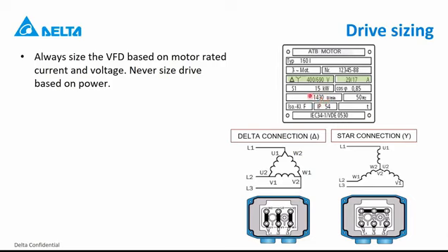So I can see, for instance, from this nameplate that this is a 4-pole motor for 50 hertz. But sometimes you get motors which are 8 poles or 16 poles or even 32 poles. In that case, the frequency is much lower, but the torque is actually a lot higher. And if you remember, I mentioned in the beginning of this training that the output current is proportional to the torque. So in those cases, you will see a current which is much higher than what you would see here. For the same amount of power, you get a much higher current.